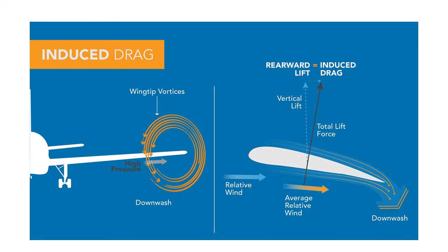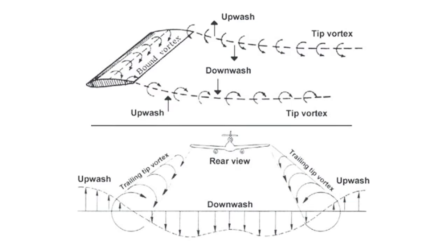To summarize, induced drag is not actually created by the wingtip vortices. The wingtip vortices are really just a manifestation of the overall span-wise flow effects and vorticity across the span generated as a result of generating lift itself. Now, this also affects the lift distribution over the entire wing because the wingtip lift has to be resolved to the free stream reference lift, or 0.